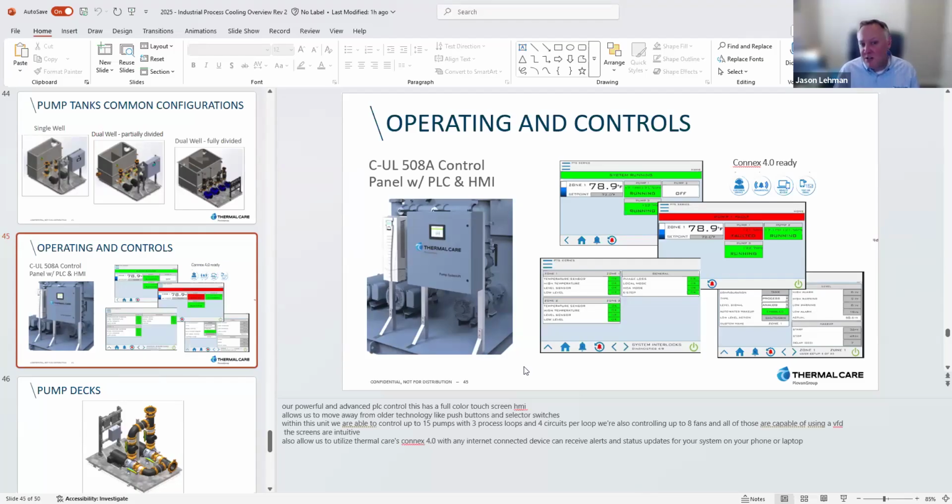A lot of times, especially in areas where there's freezing with cooling towers, because you want your cooling tower to run in the winter as part of the process, we need to control the cooling tower fan and also the cooling tower pump, so that we're not sending 40-degree water out to a cooling tower that's in minus 20 degree ambient conditions and freezing up the tower. So basically we'll stage the fans or put a VFD on the fans to control that. And when the water temperature doesn't get cool, we'll actually turn off the cooling tower pump and have all the water drain back inside until we start sending the water back out to the tower.